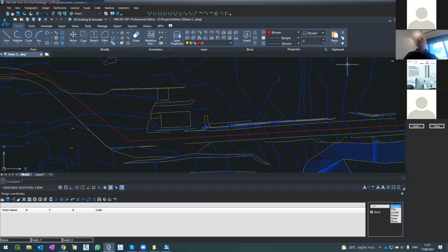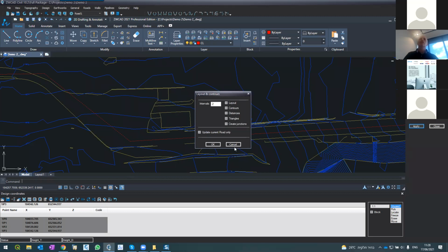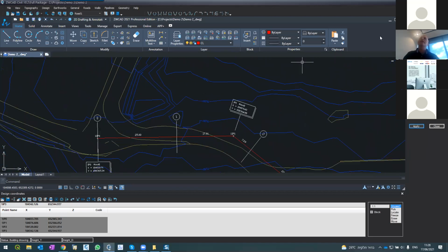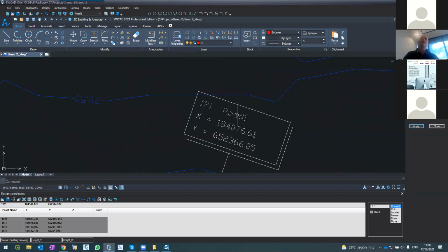Here on the right, I'm selecting the polyline and pressing enter, and automatically it creates IP coordinates. You see here, IP coordinates, and convert this into a road. So you see what happened. Once I selected it, the software is now becoming a beam module of a road with all the cross sections and the data on the IPs.